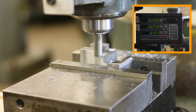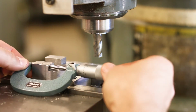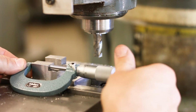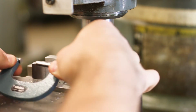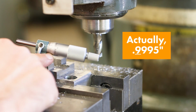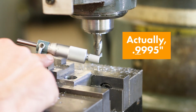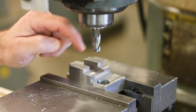Okay, final measurement here. Okay, so 499 thousandths and a half, 0.4995, or something very close to that. So definitely within tolerance there. Okay, moving on, let's not forget about the tops of these two tabs here.